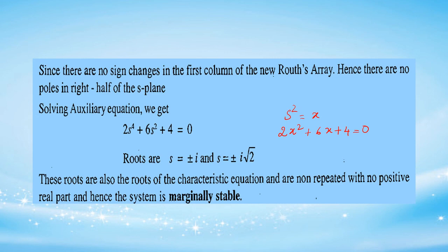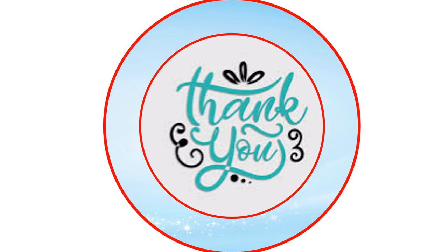So we have solved the special case of Routh array by framing an auxiliary equation, getting its derivative, substituting the coefficients of that derivative in the row which has completely 0, and checking the stability of the system. Thank you.